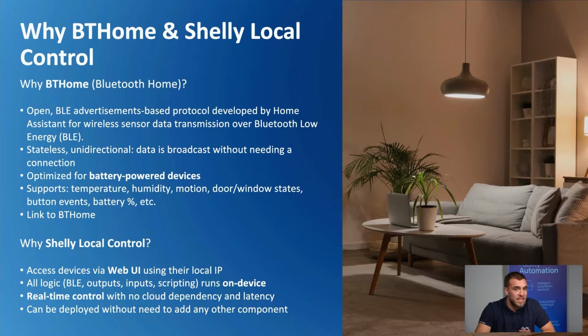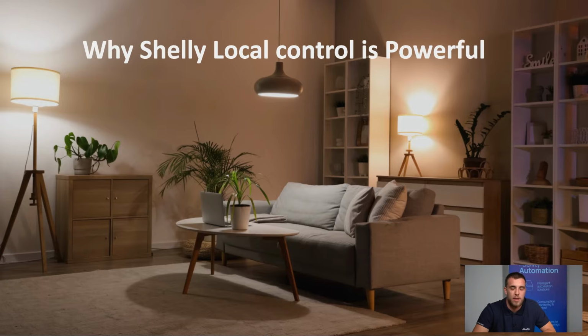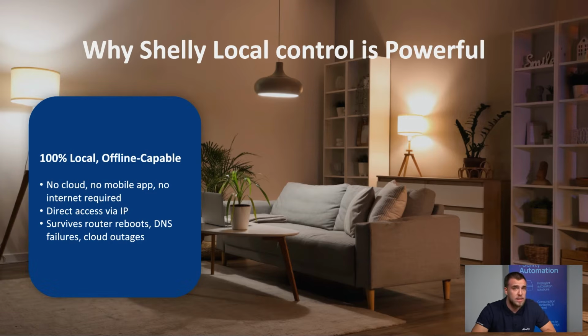And it's fully manageable through the local control of the Shelly, where the user interface can be accessed via the IP address of the device. So, as I just said, it's absolutely offline. It's only local, so you don't require any cloud, mobile app, or internet. You can directly access the web interface via the IP address, and thanks to that, you avoid any Wi-Fi router reboots, DNS failures, cloud server outages.